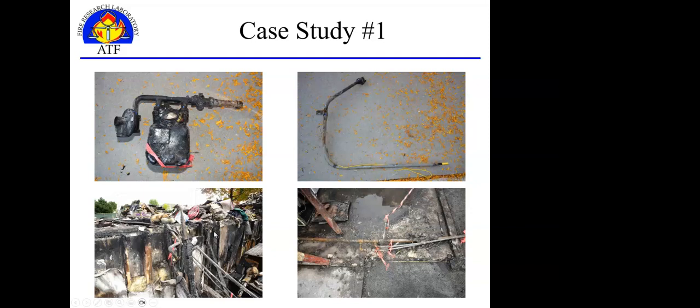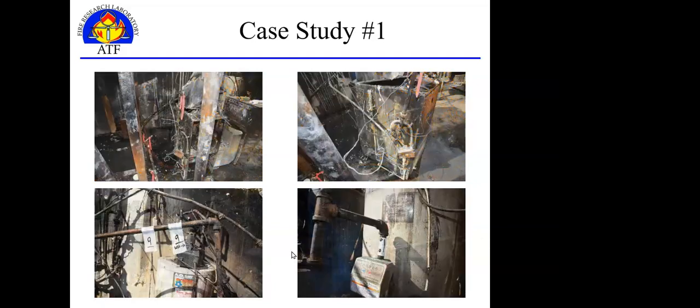So in this case, they got all the debris off the structure. We were able to get into the basement and look at all the gas piping. Here are examples of how we documented. We cut all of this piping. So in this particular instance, we used tape. We numbered everything. So 9 went to 9. This is denoting that this goes to the water heater. Here's cut number 10. And we put a line here so you could match those cuts back up.